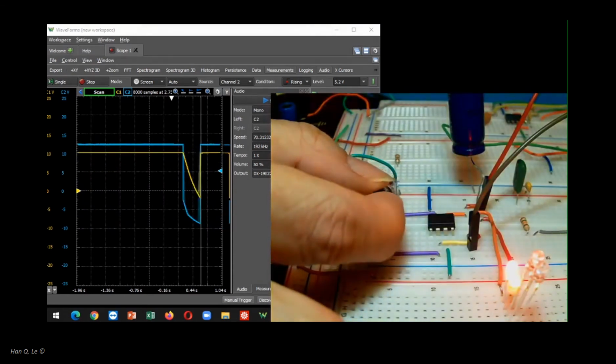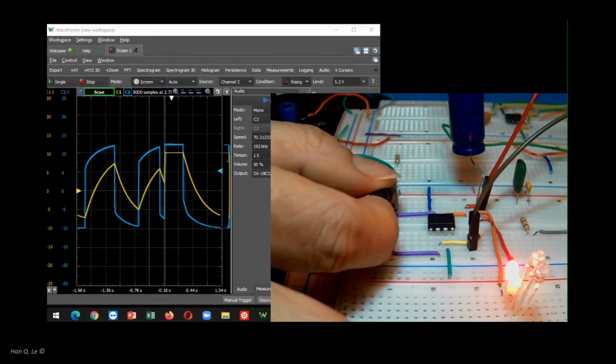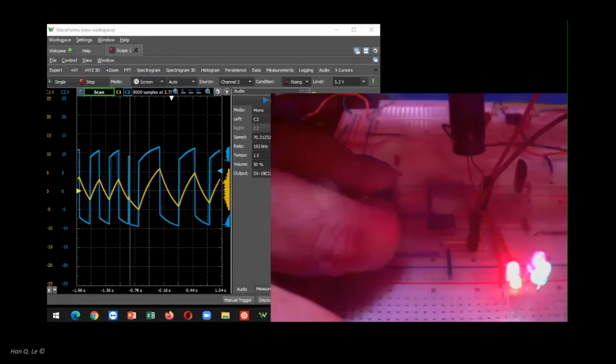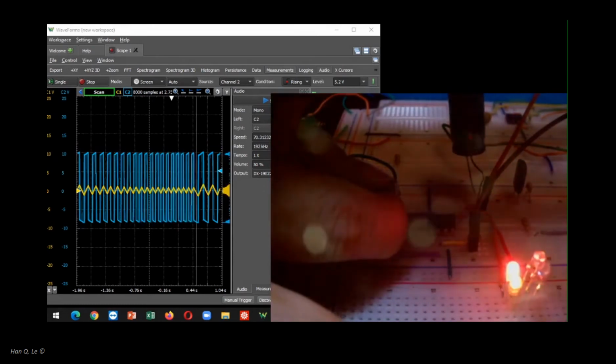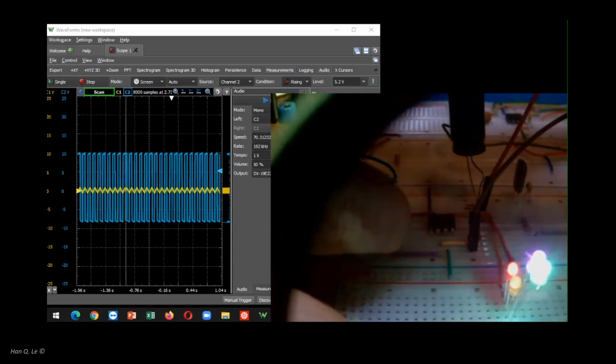Beware of a possible small hysteresis effect, that is, the blinking frequency when sweeping up might be slightly different when sweeping down, when the potentiometer is set at the highest capacitor voltage. Best is to always sweep in one direction when collecting the frequency data.